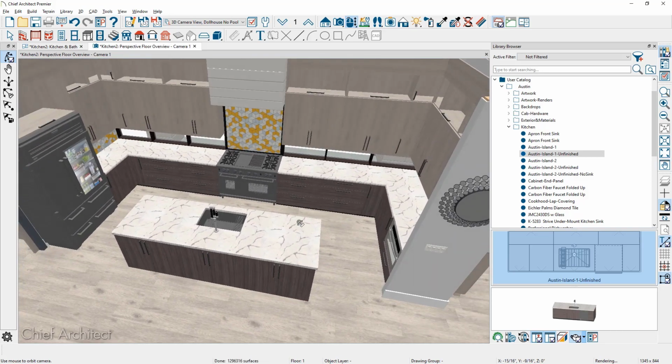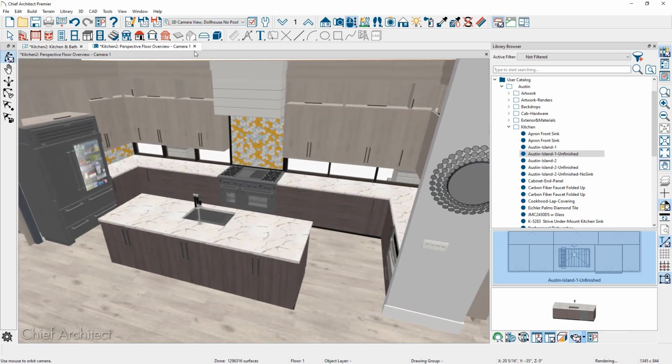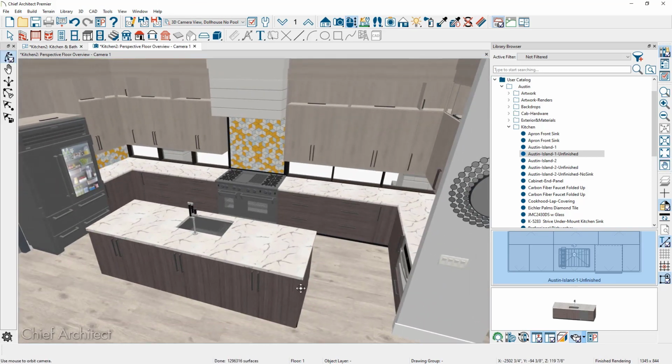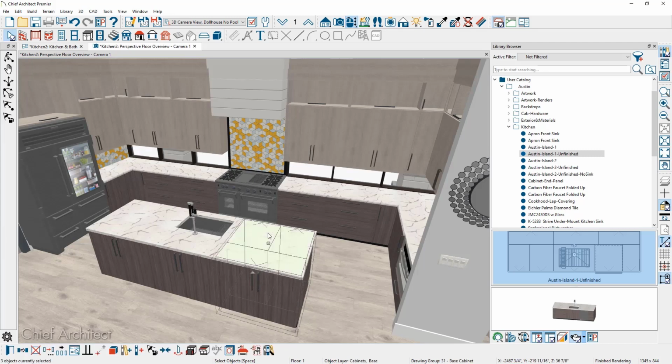So we rotate around just a little bit and look at the side of the cabinet. I want to create a waterfall that will come in here. You can waterfall with the automatic tool when the countertop is a custom countertop. To create a custom countertop from this particular island, I'm going to hold my shift key down and just grab all of the cabinets that make up the island. When they are selected, there is the option to generate a custom countertop.